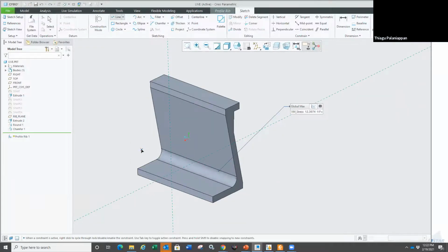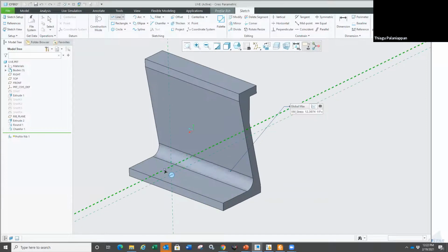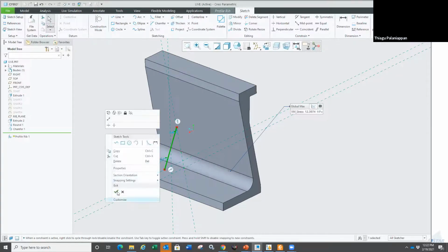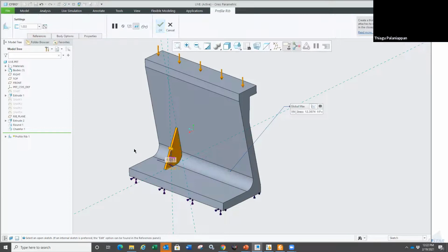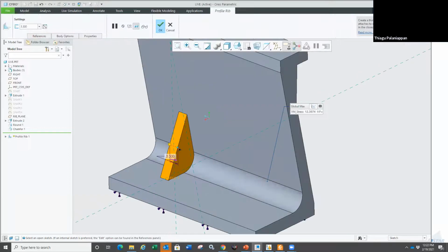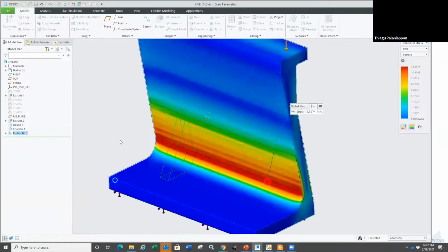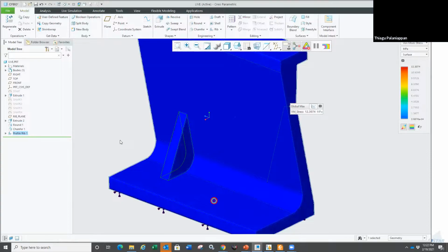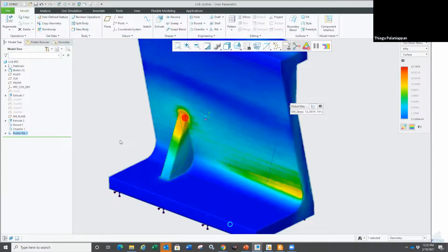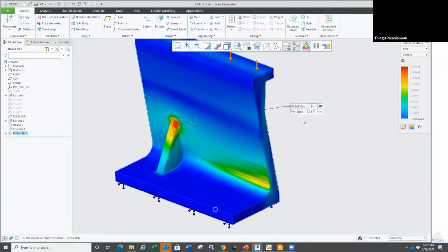So I'm going to add, just use the Alt and grab these guys real quick. Holding Alt essentially allows you to select references as you sketch. Right, there it is. Just did an open sketch, because for a profile rib you have to have an open sketch, right? So these are all regular design things that I'm doing here. And once I'm done, the analysis was on, right? It kicked in and brought it up, actually from 12, it's back up to 17.